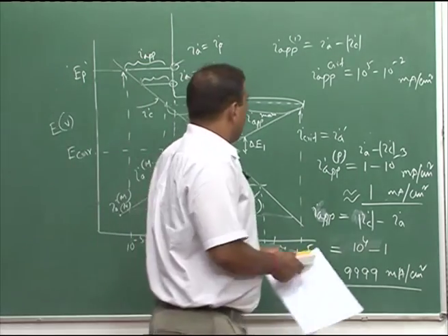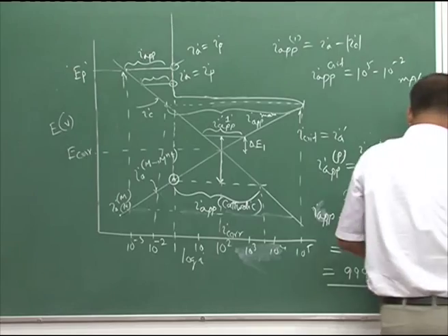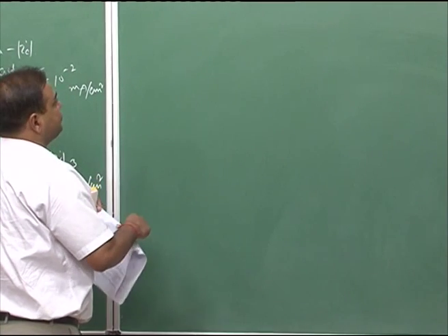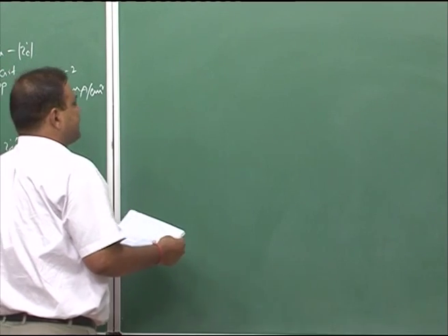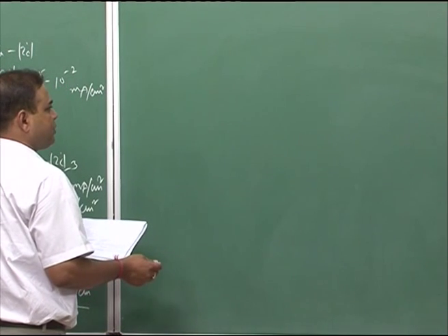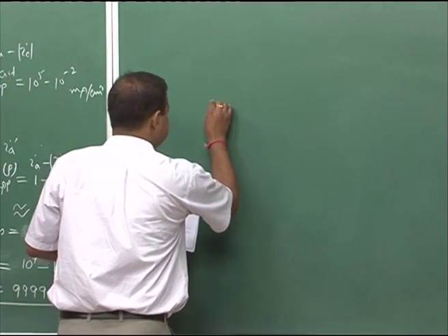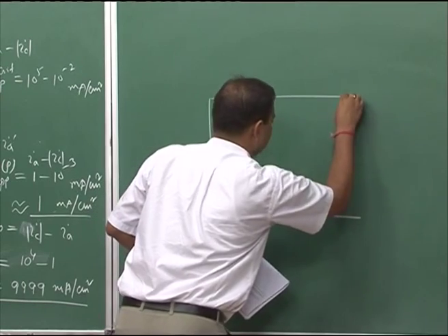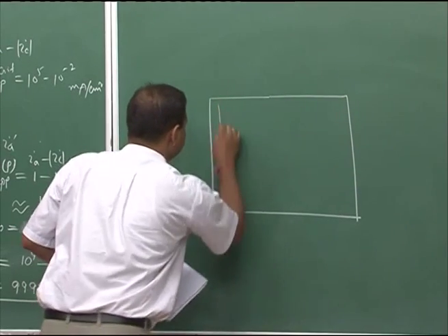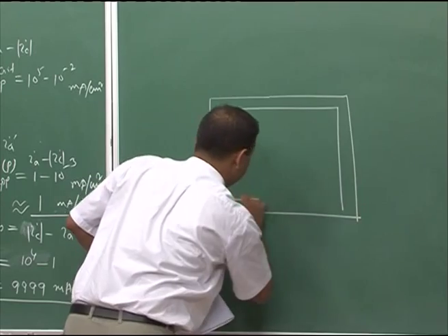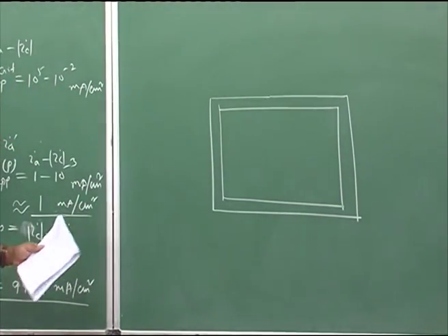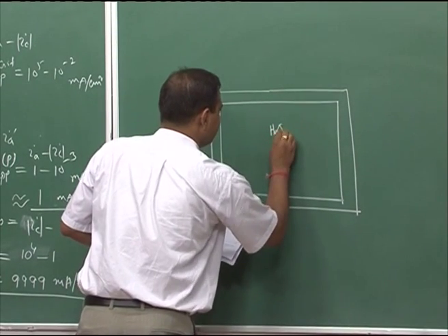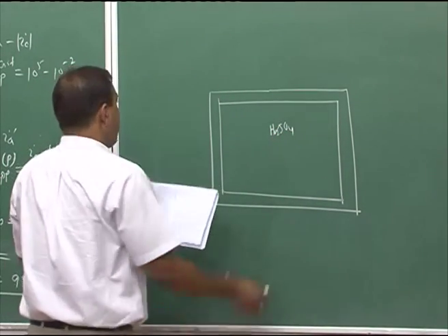Now, if we see the experimental arrangement, the way we should increase the potential of the metal object which is to be protected anodically, that system is shown here. Let us say this is my steel tank which is to be protected, and this steel tank contains H2SO4, and we should have a potentiostat.